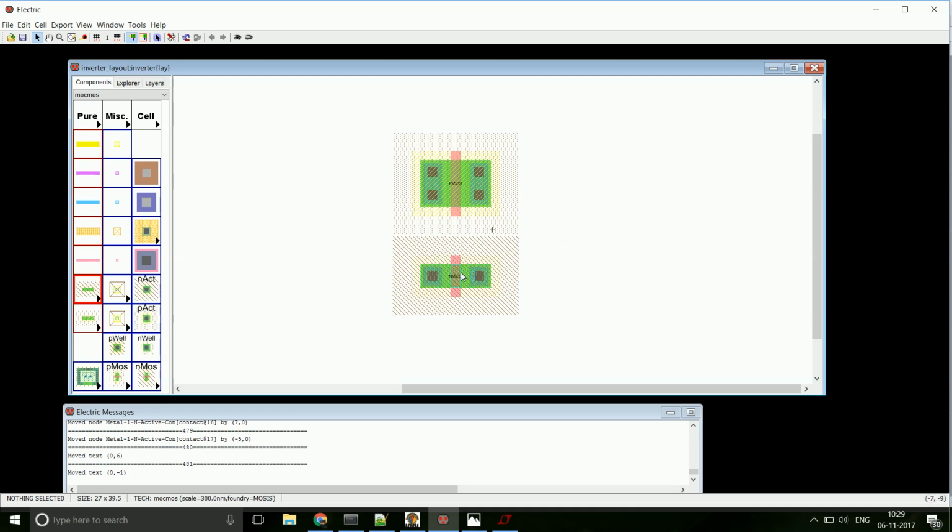But if you can achieve a proper overlap, always go for it. But that's not the aim of this tutorial. And so yeah, we've done the PMOS and the NMOS. Now let's make connections. I'm assuming this is the drain. I could easily assume this is the drain of the both. So click on one, right click, extend down to the other, lock down, done.